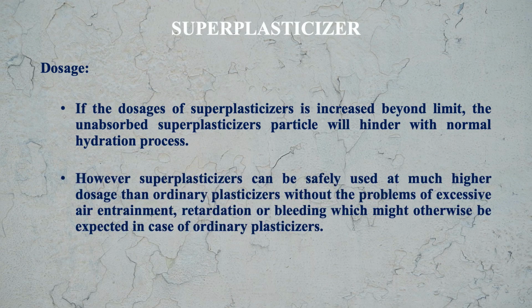However, superplasticizers can be safely used at much higher doses than ordinary plasticizers without the problem of excessive air entrainment, retardation or bleeding, which might otherwise be expected in case of ordinary plasticizers.